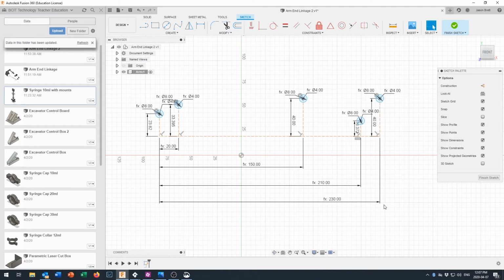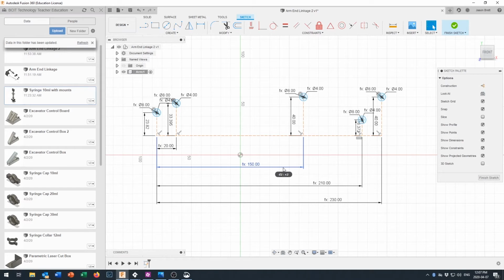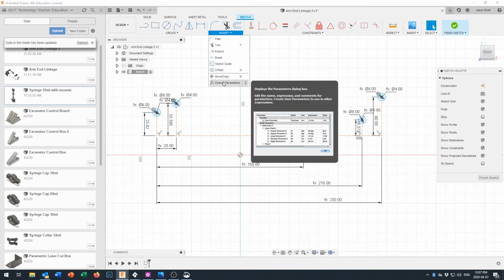and press enter. Now, depending on how long your shape was, it may be a better idea to set this one first, or you might have to play around with them in different sequences depending on how you've got them set up. What's nice now that we've parameterized all that is that later on when we're trying to piece this arm together, we don't have to come back in and edit this sketch. We just go to modify parameters, and all of our parameters are sitting in one spot waiting to change. Let's add the Y dimensions as parameters right now.